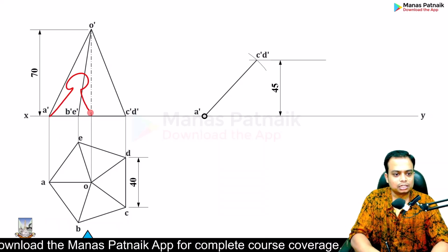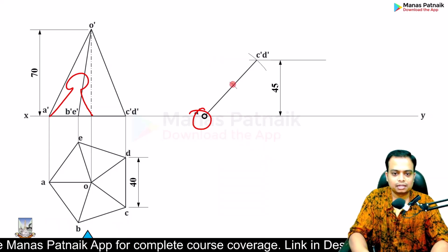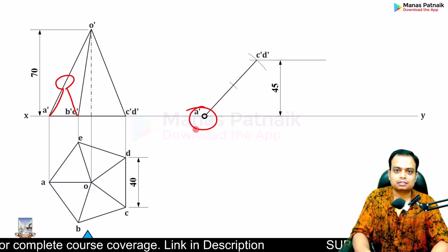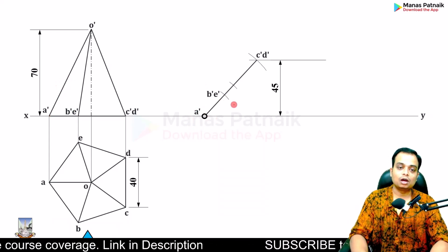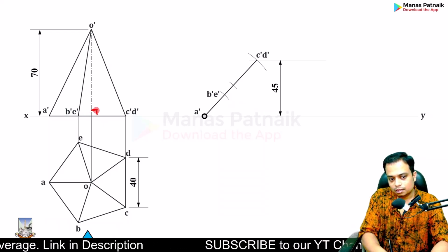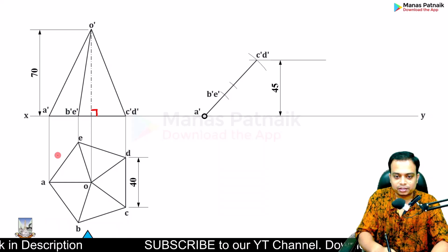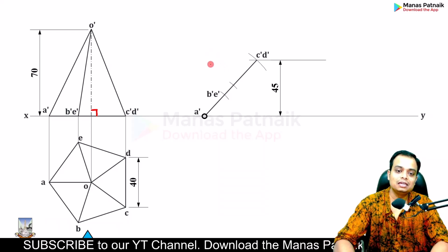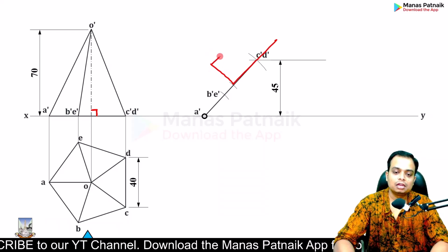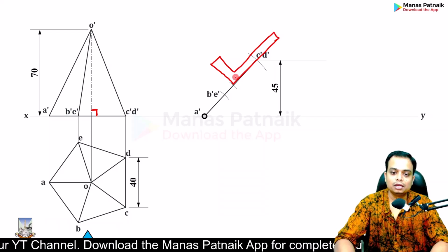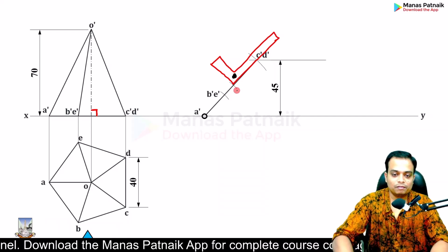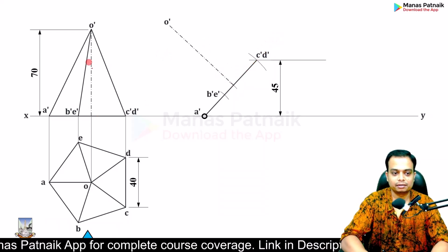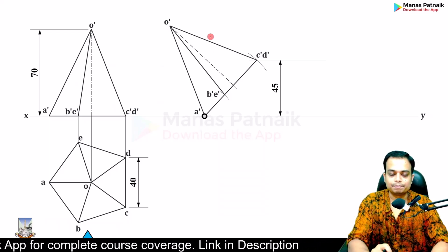Now this much as the radius, again A dash as center, cut an arc again. That is the location of the base of the axis, and then with this much as the radius, and with A dash as the center, cut an arc again, and that's B dash E dash for you. Now the axis is at an angle of 90 degrees with respect to the base. So you need to make an axis like this over here. Okay, you can do this very easily using your mini drafter. Keep it over here in this position, and then lock the screw as always, and then draw a line like this. Can you do this? Yes, sir, we can. It's very easy. And then you need to again make these lines. So damn easy.